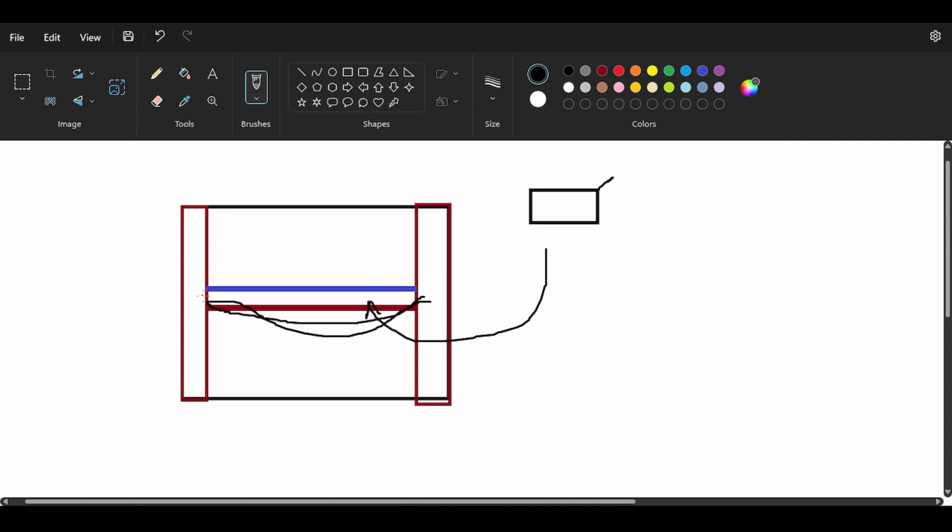Or, if I design it to be a beam, then a foamy or springy or spongy material is put between the blockwork and the beam, so that there is no load transfer between the beam and the blockwork. Because if you just put block and then cast the beam on top of it without any separation, then if the structure gets overloaded, you will have cracks in the bricks, because the bricks are not designed to carry the load of slabs and staircases.